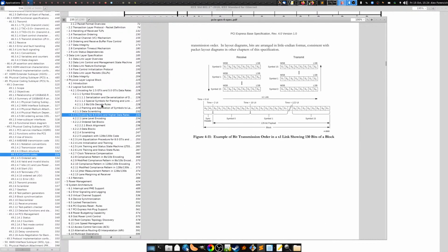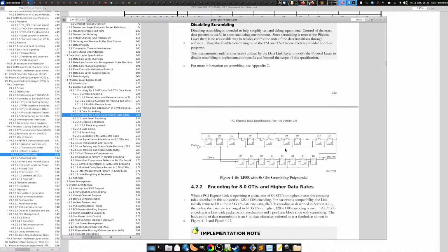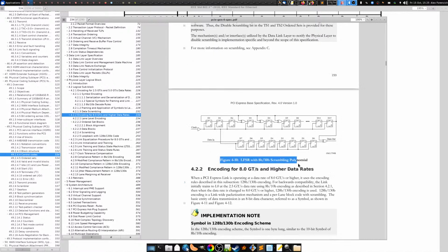Yeah, so the other thing I should mention is that PCI Express also uses scrambling, but it does the scrambling in a completely different way than Ethernet. So this is what the scrambler looks like for PCI Express for 8B10B. This is for Gen 1 and Gen 2. As you will notice, the data input doesn't go through the actual sequence computation. So basically what you're doing is you're taking the sequence, right? And then you're just XORing it with the data. Apparently with an 8-bit delay.